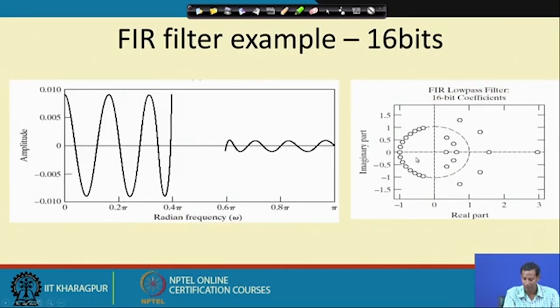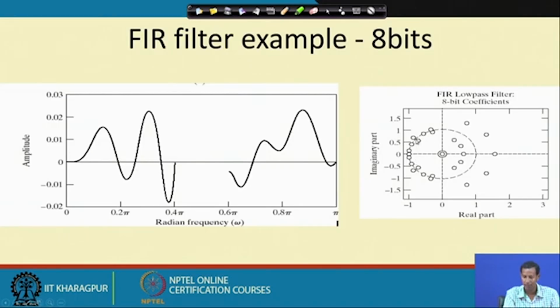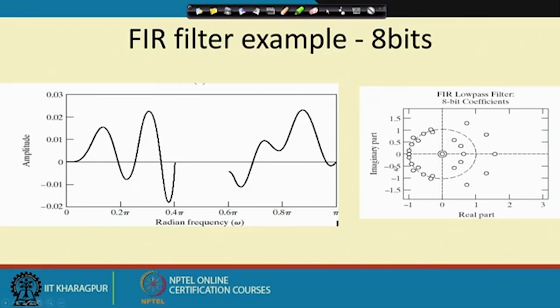So, that means the performance is sometimes going beyond the unit circle. Okay. So, that means the filter whatever you have implemented in hardware may be unstable at that time. So, it is not advisable for the filter hardware to be designed considering that each of the coefficients is of 8 bits, because the performance of the filter may be unstable. So, in some cases it may be unstable.